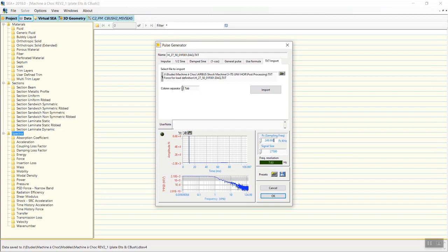And above 20 kilohertz, typically we expect background noise because the force is too low. And then obviously the limit of the calculation of the acceleration, the validity of the measurement, the limit of the measurement is about 20 kilohertz.